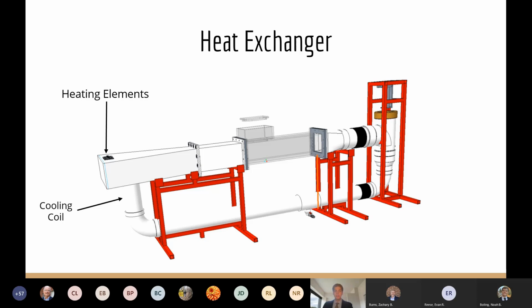The heating elements have been placed at the top of the plenum section, behind the flow as it comes into the flow straightener. This was done for two reasons. For one, this will avoid a high pressure point where the elements enter the flume. Had we placed the elements directly above the PVC's direction of flow, there was a chance of breaching the seal where the elements are connected.